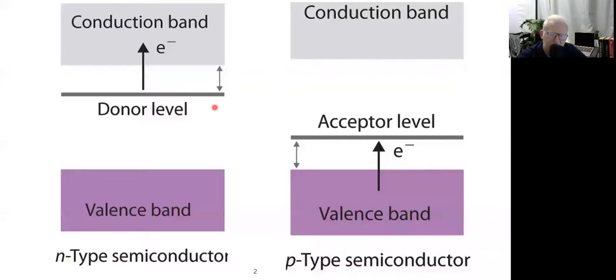Okay, so at the conclusion from the first lecture, we have studied that whenever there is a doping, this doping is generally reflected on the position of the Fermi level. I mean, for an n-type semiconductor material, we should expect that the Fermi level will go nearer to the conduction band rather than to the valency band, to indicate that the number of electrons is greater than the number of holes. Vice versa happens when we go to the p-type material. I mean, whenever you dope your material with an acceptor, a third group material, the Fermi level is going to go downward to be nearer to the valency band with respect to the conduction band.